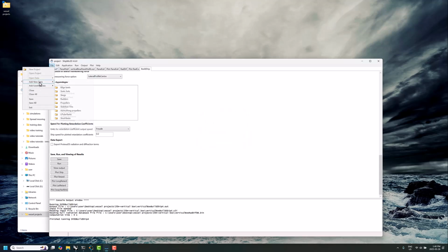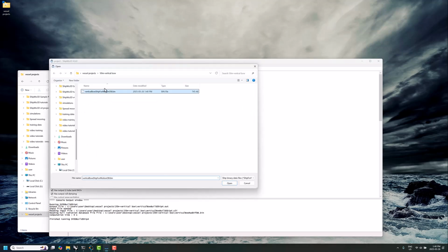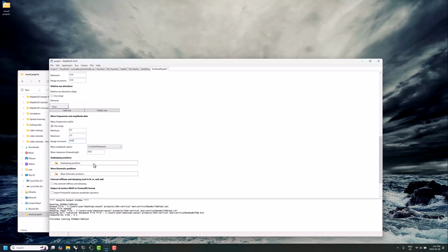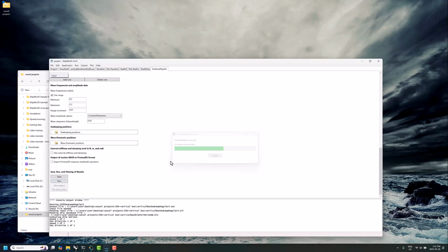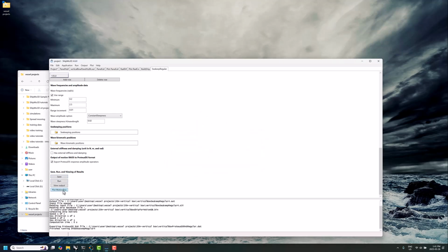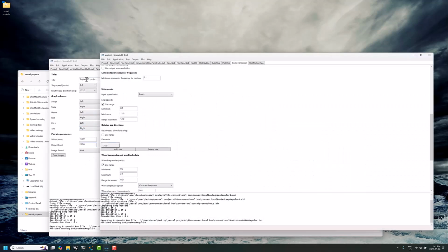And we'll likewise go to add new data, SeaKeep regular, pick our ship model file, there you go, and put in 12, increment to 12, just do 135, make this a little bit higher resolution, so we do up to 2.5, and remember we changed this to be a little bit of a higher resolution increment for the motion RAO files. Oops, we forgot to check this box to export that, so we'll run that, plot the motion RAO. Okay, that's looking good.